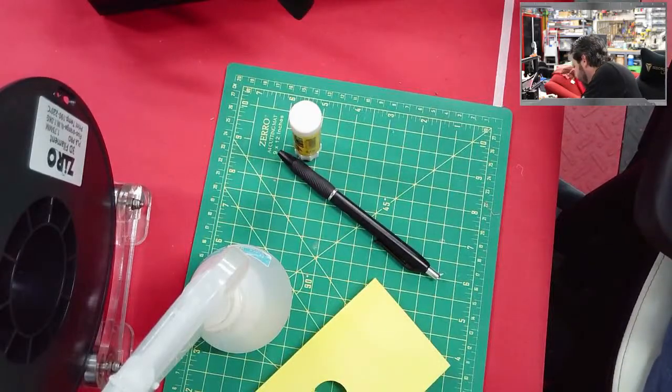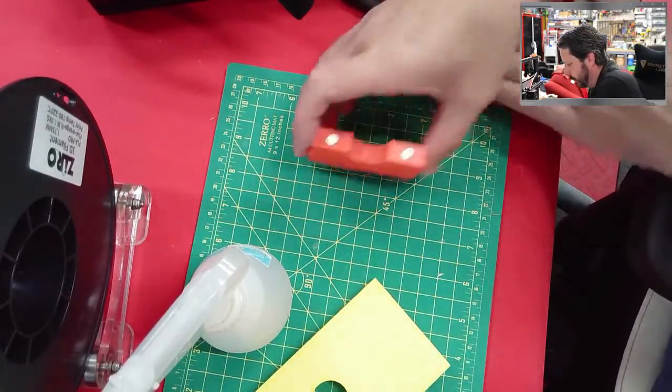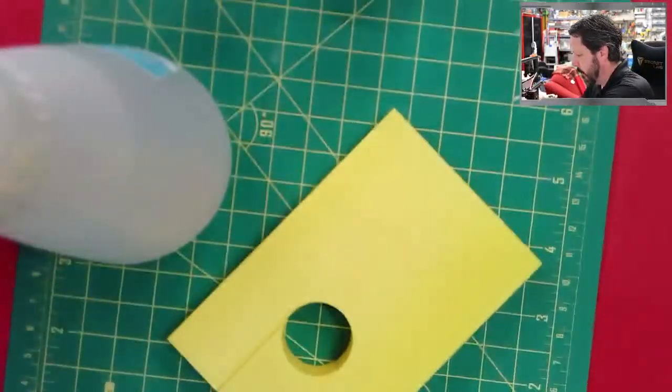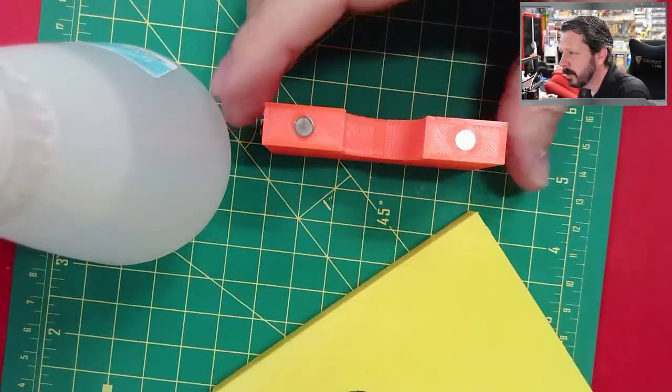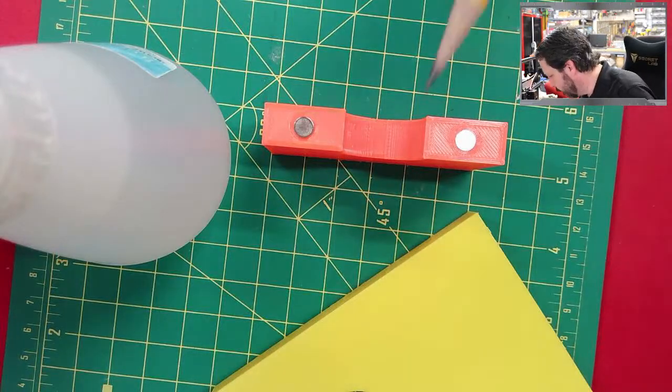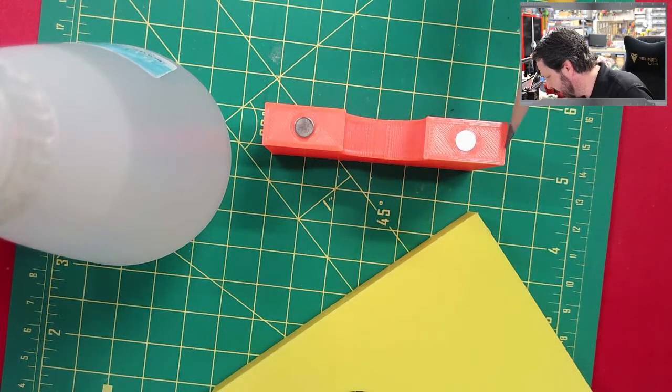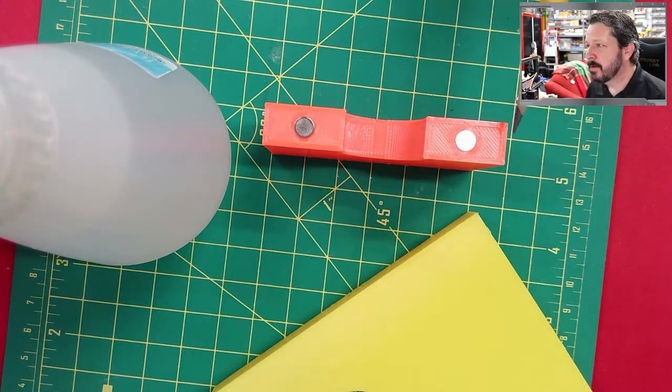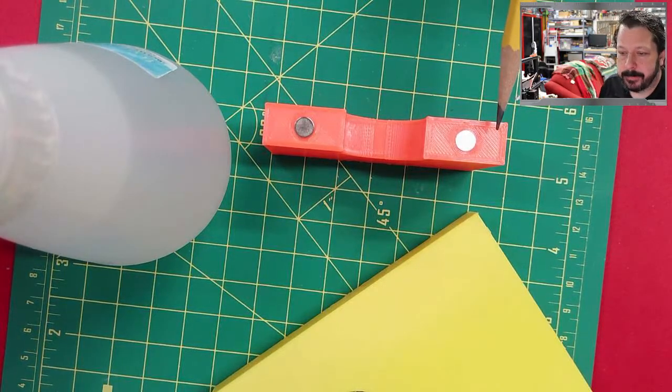I think you get the idea of the walls, but just in case, let's go down close to it. So yeah, you can see the walls there. See how there are a couple of straight lines on the outside? For this print, I wanted to have 3. I generally would have done 4, but this is a relatively small print, and walls are slower to print, so every wall you add does add a pretty significant amount of time to the prints.